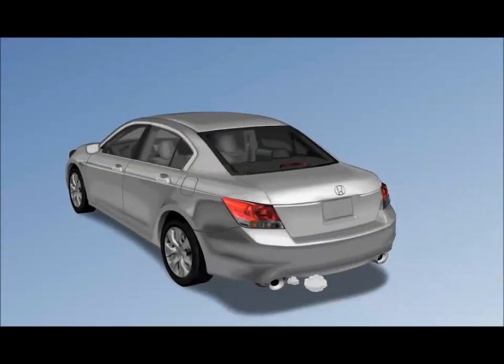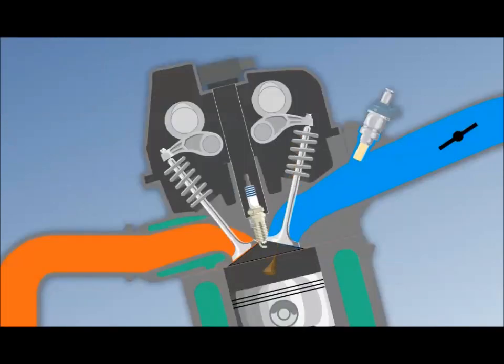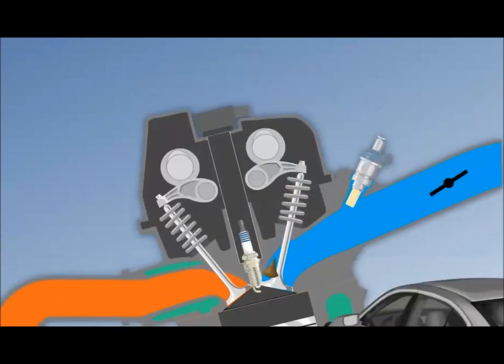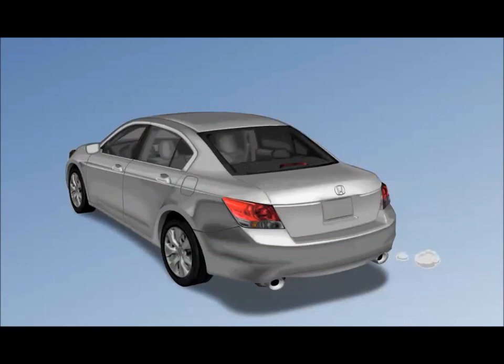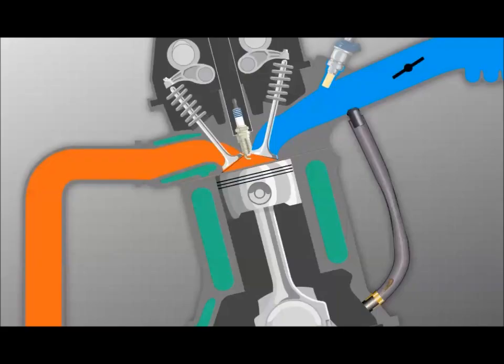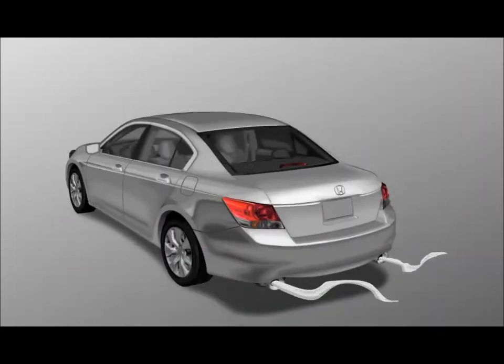A vehicle that produces oil smoke at engine startup has oil dripping onto the intake valve through the valve guides. A small pool of oil accumulates on the intake valve and creates a puff of smoke at startup. As the valve stem seals and valve guides degrade further, they begin allowing oil into the combustion chamber during high vacuum conditions.